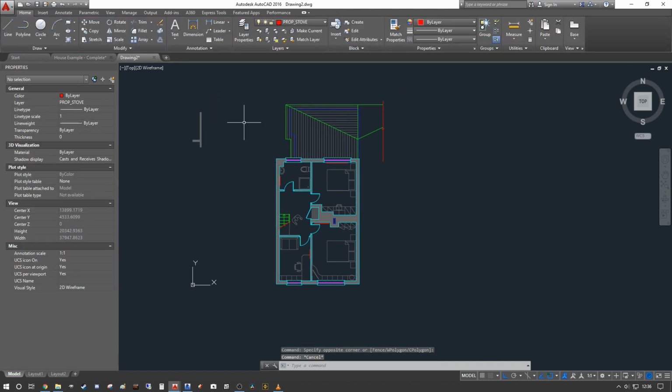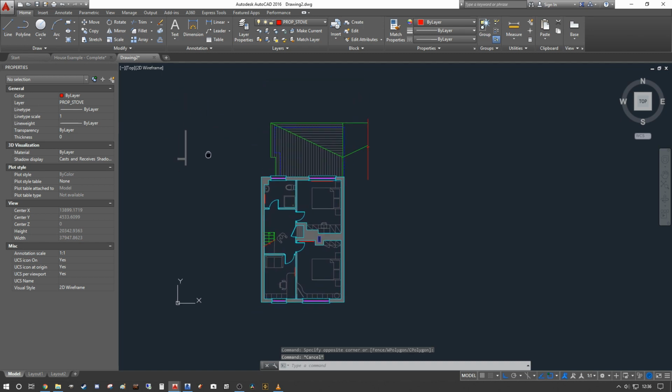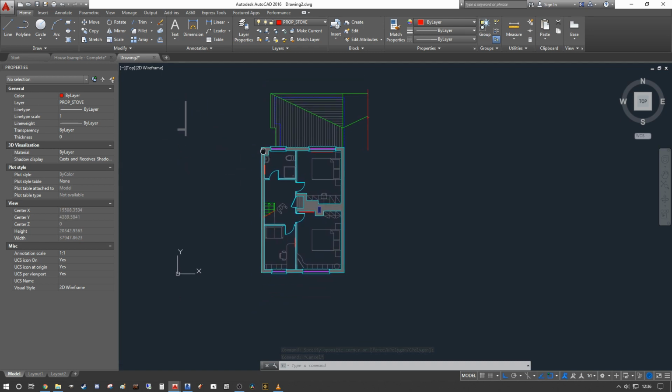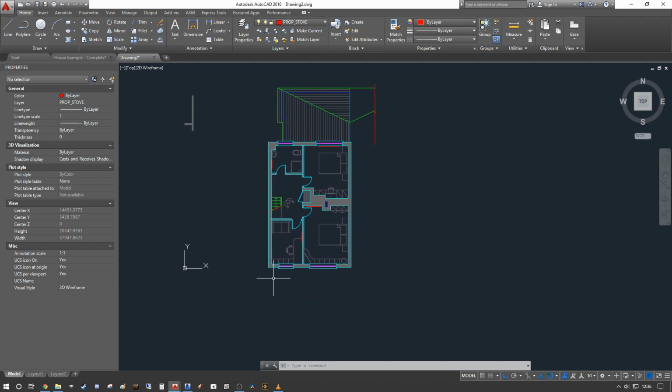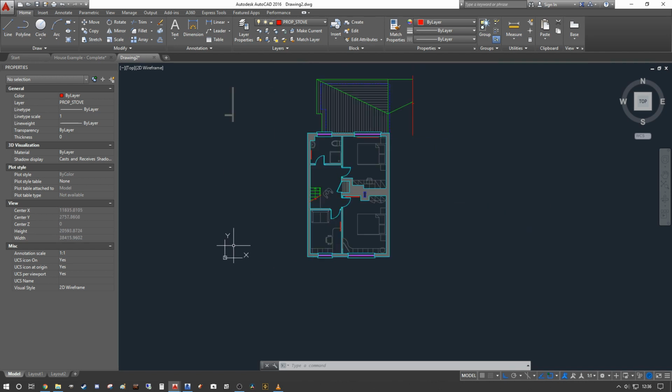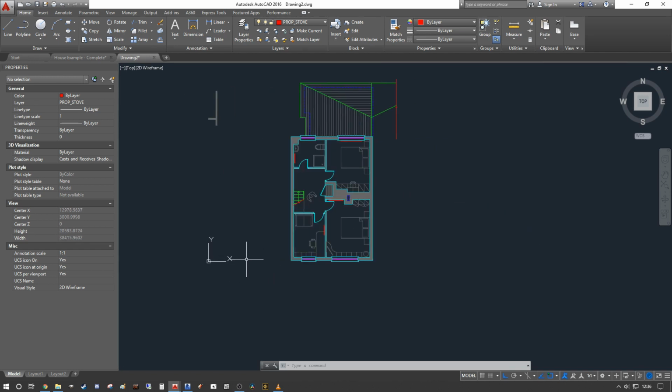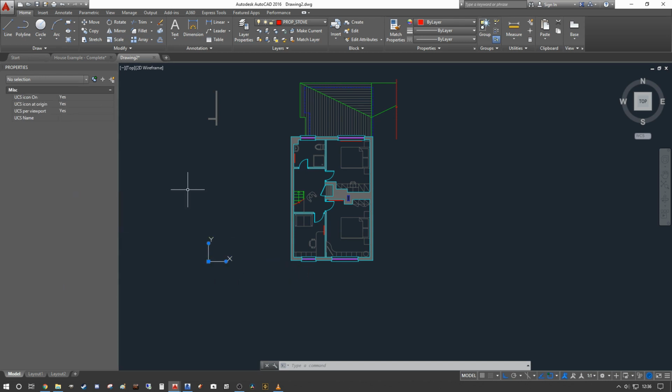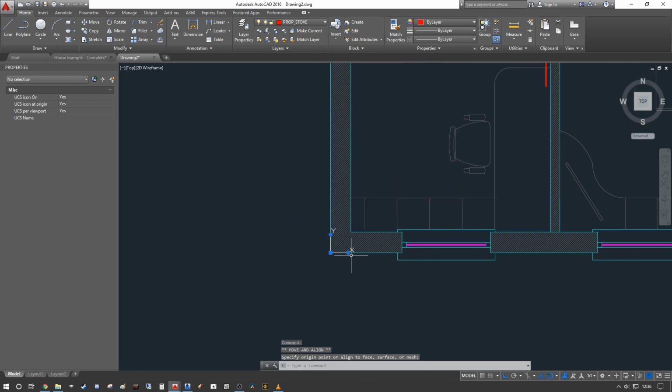So in this instance, this is stray, so we're just going to acknowledge that we can change that in the Revit environment afterwards. But what we want is a consistent point in Revit that we know as we proceed up through the floors will remain in the same position. So we're going to look to this front corner of the house here, and what we're going to actually do is select our origin, and relocate that to snap to the endpoint of that there.